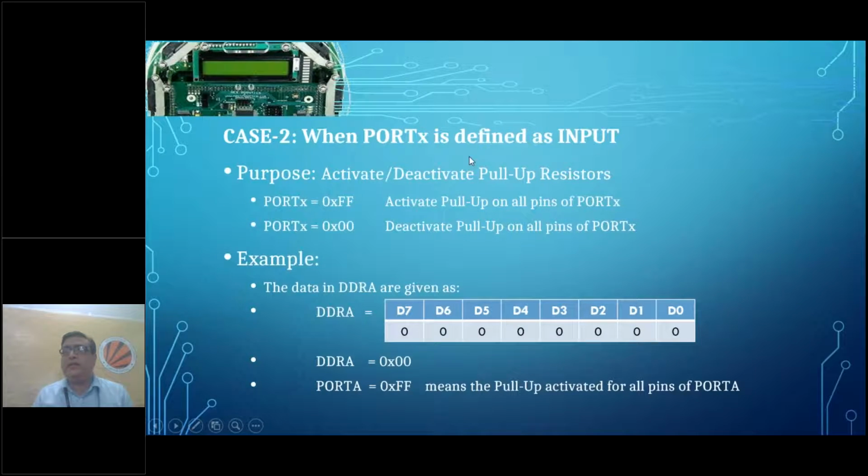Similarly, case 2 is when port X is defined as input. When it is defined as input, we are just activating or deactivating the pull-up resistors available on that chip. So if the PORTX value is 0xFF, that means all the pins are activated for pull-up.